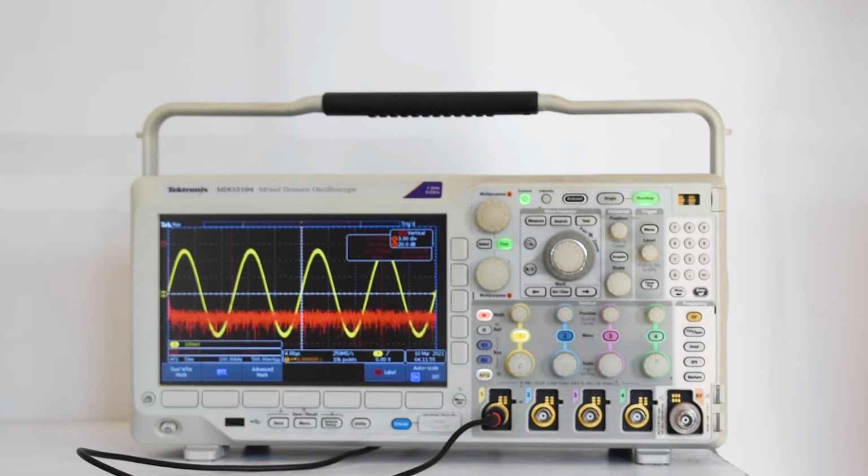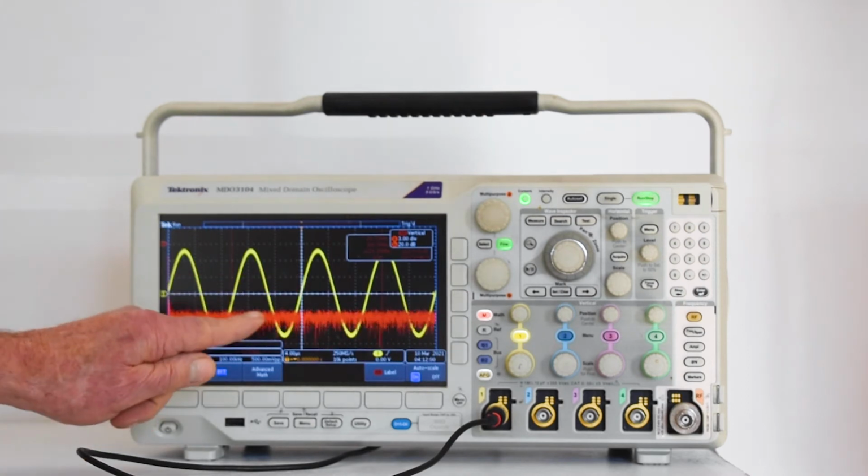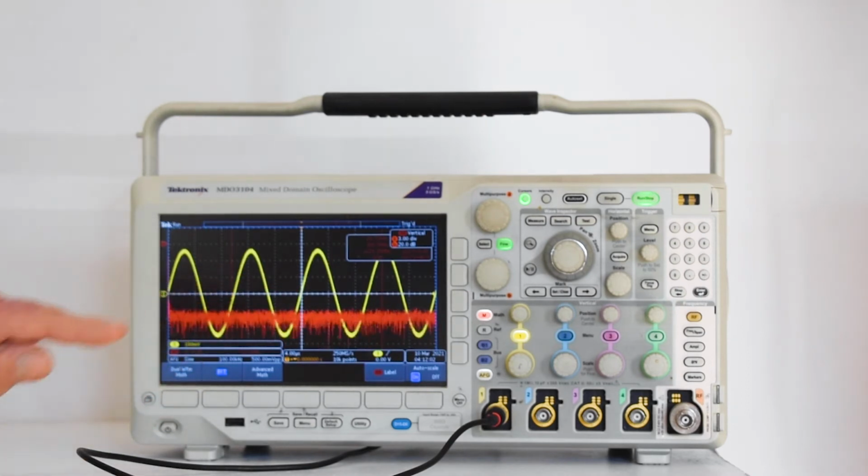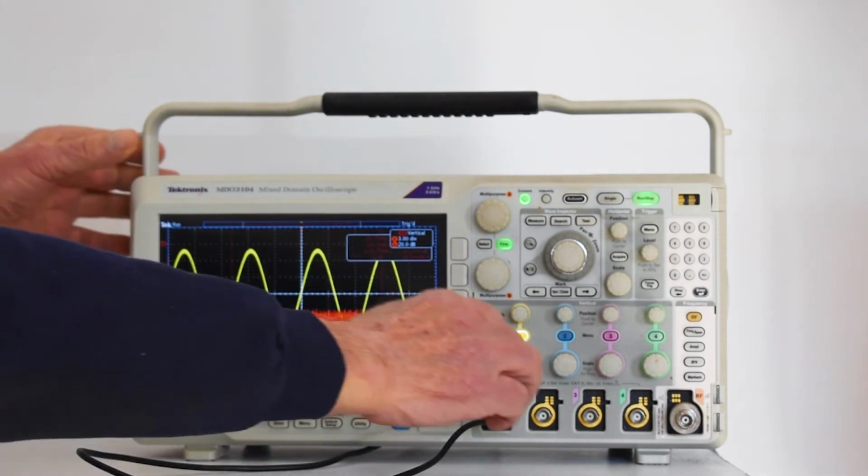The irregular fluctuating trace at the bottom is the noise floor, similar to the snow you see on the screen of a TV when it is tuned to a channel that is not active. The sine wave fundamental is concentrated at a single discrete frequency. You may not be able to make it out because it is crammed against the edge of the display.